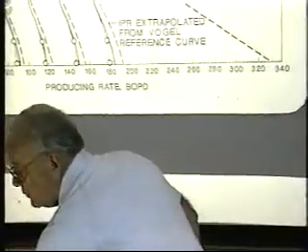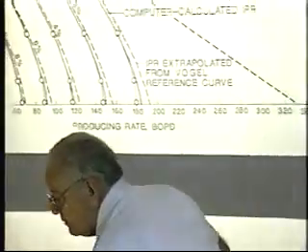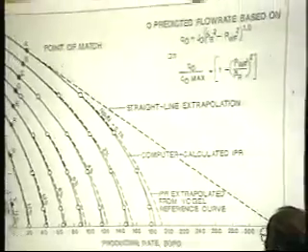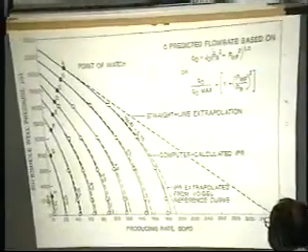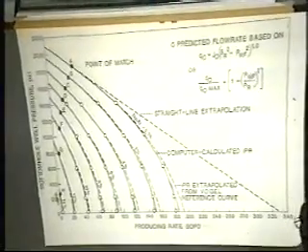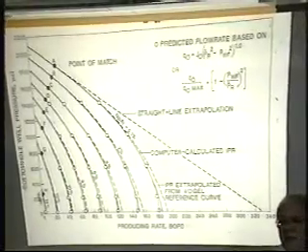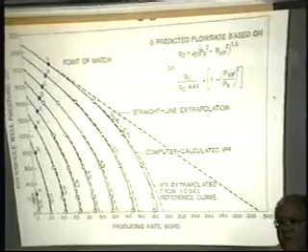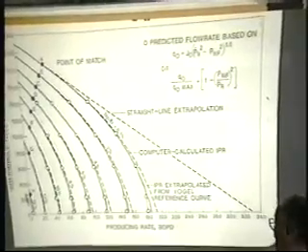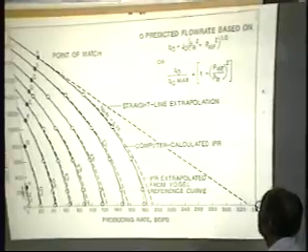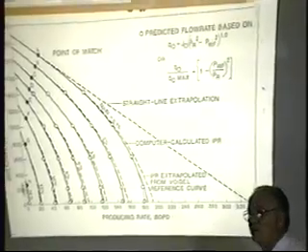This is oil well inflow performance. This is the Vogel curve. With data off of Vogel, he built a model and he ran a bunch of cases for different types of PVT properties and different solution gas drive reservoirs, and he came out with an inflow performance equation.